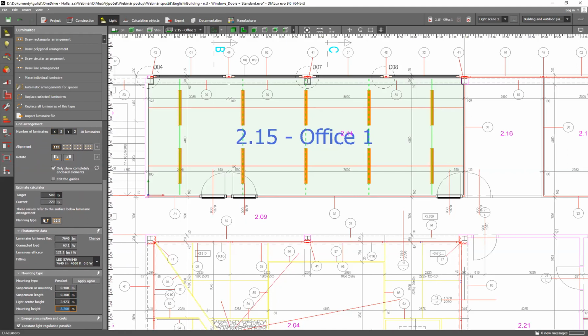It's going to be fine. Because if you do it in a different order, you draw a room, then import luminaires, and after that you set the ceiling, you could have luminaires out of the room, between those 2 ceilings.